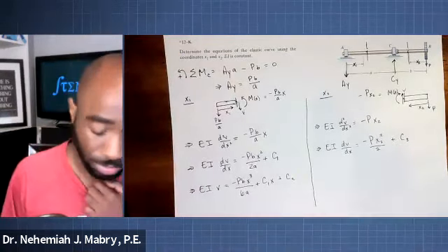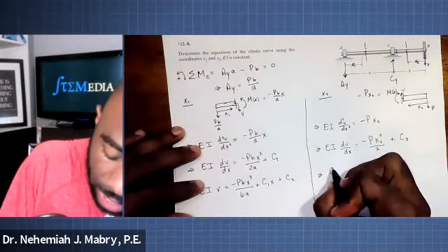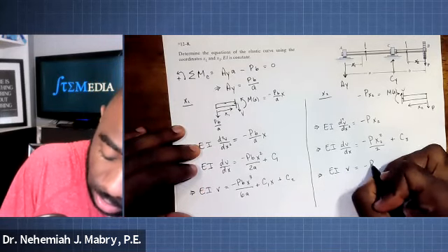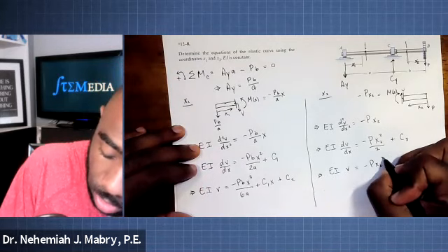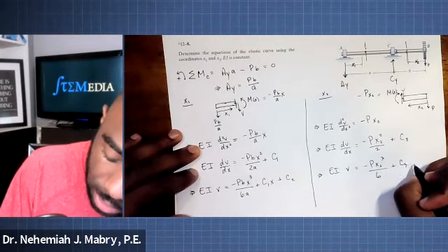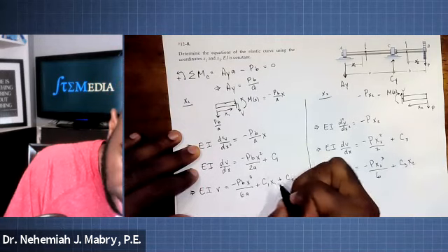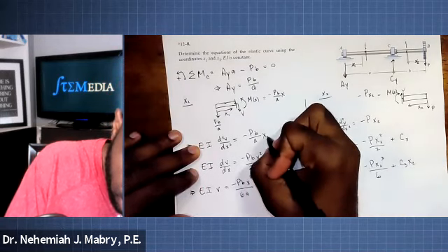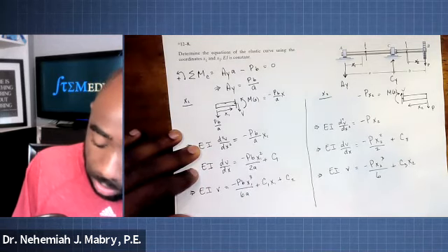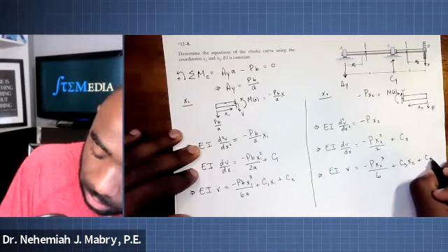Make sense? All right, and then the displacement equation, it's going to be EI V equal to negative P x2 cubed over 6 plus C3 x2, right? We're calling these x2. We can call all these x1 if you want to keep it distinguishable, right? All these are x1s, all these are x2, plus C4.